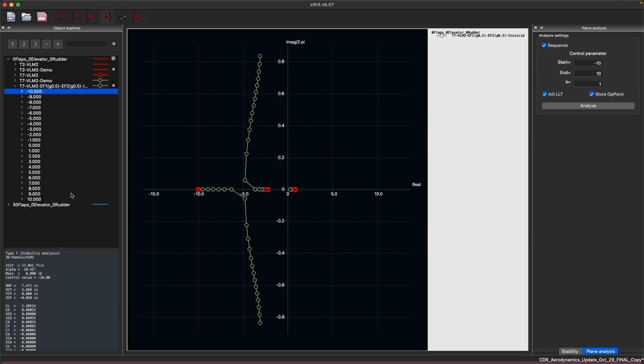Oh, actually, this is exactly what the gain is doing. As you apply the gain, the root locus will move, and this is where your breakout point of your root locus is, and then you will start to grow out on the imaginary axis.